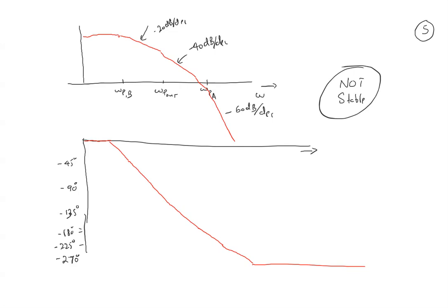The system can be stable only if we can do something with this Y now. For a 3-pole system, if we play around this area of minus 270 degrees, it's not going to be stable. We want our unity gain, this 0 dB point, wherever it becomes, because we don't have the numbers here, to come in this area where the phase crossover frequency is.